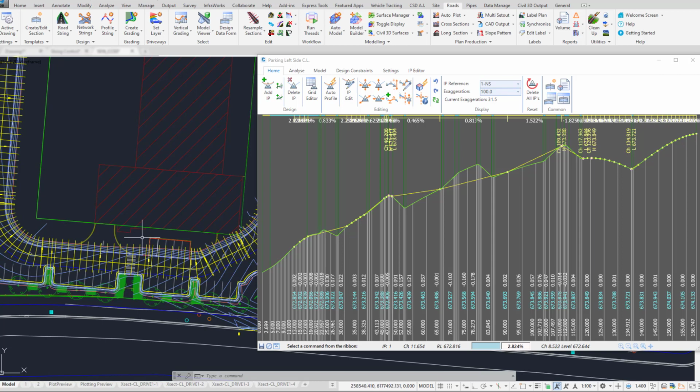Now typically at this point you'd go back to auto profile, click on calculate profile to close the form. However, you can now simply click refresh, and when you click refresh it rereads the reference for you immediately.